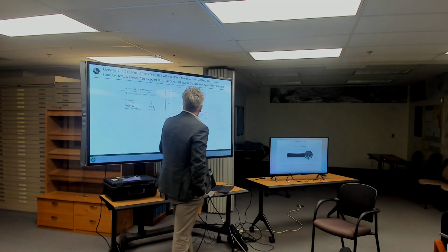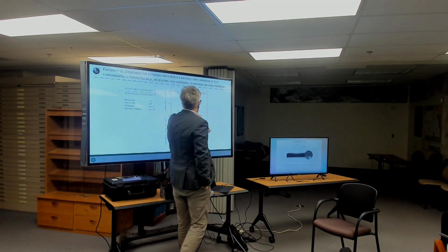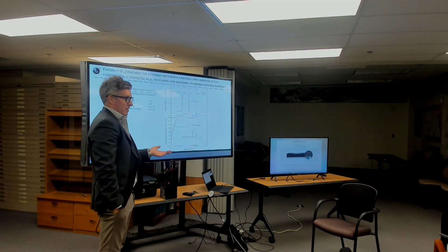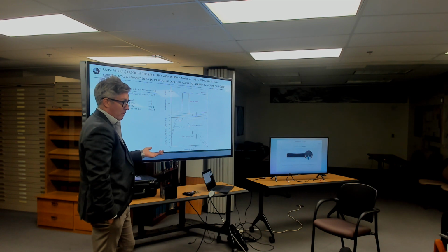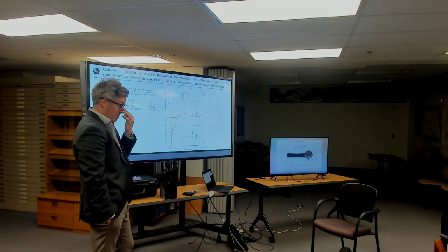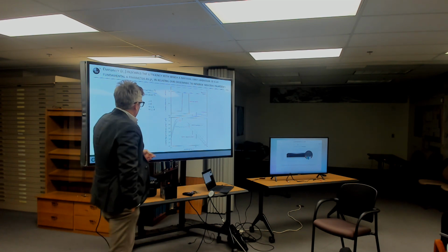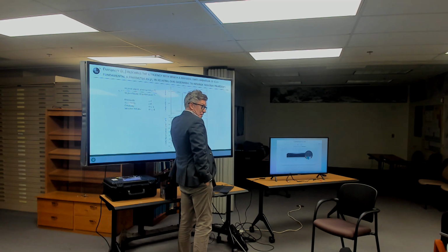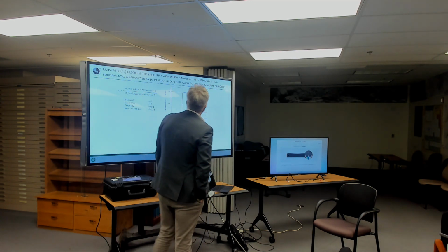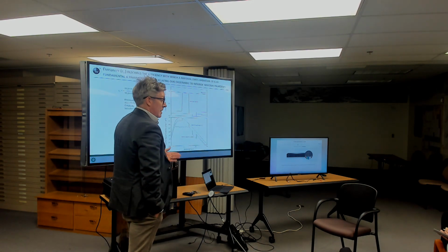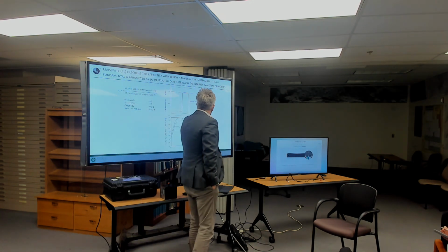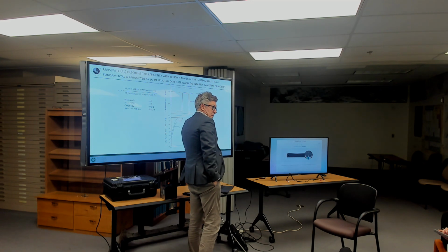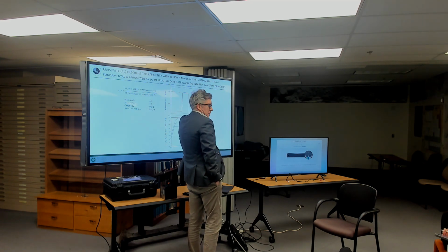If we look at this wavelength at about 2 microns, my selective radiator behaves almost like a black body, right? It radiates almost as much as a black body at the same temperature. Which makes sense because at those wavelengths, the red curve lies on top of the black curve. The wavelength at which my selective radiator is least like a black body is here, about 10 microns, right? Because the emissivity is down close to 0.